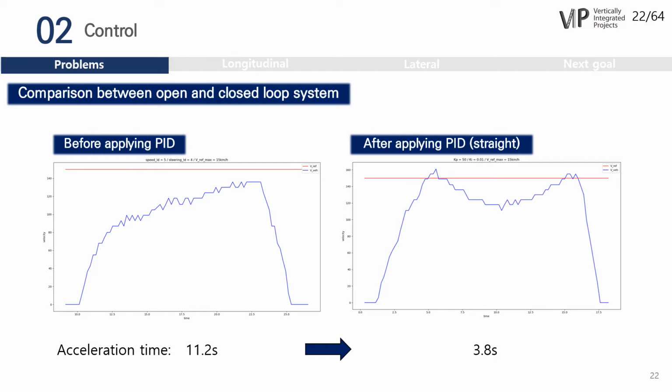Through this semester, we found that our vehicle reached the target speed too slowly. So no matter which target speed the ERP takes, we try to make it get to that speed as fast as possible, then maintain the speed with stability. For that, we set the p-gain value up. As a result, we got this graph. The problem was though, after it hit the target speed, it loses its output for seconds. We thought that was because there might be some problems in hardware or small sync on the track might affect.